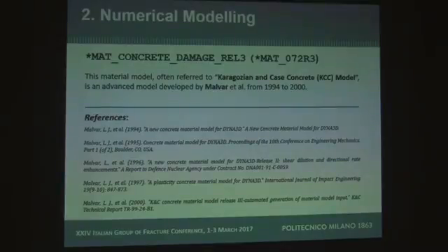As a material model, we use the KCC material model, the Karagozian and Case concrete model. In LS-DYNA, the keyword which defines this material model is called MAT_CONCRETE_DAMAGE_REL3 or MAT_072R3. This material model was developed by Malvar.